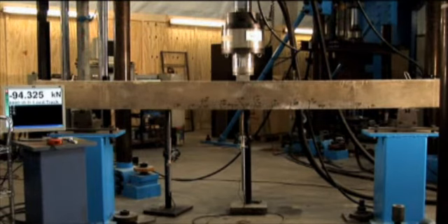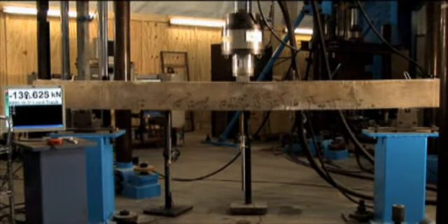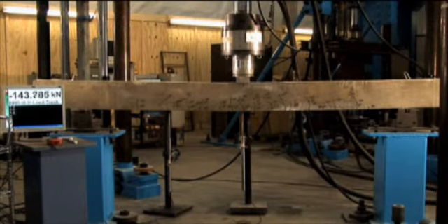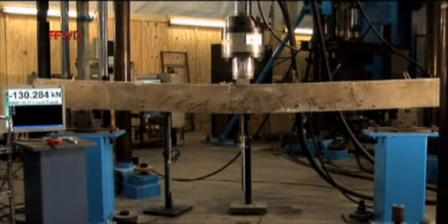As the beam approaches failure, crushing of the concrete occurs, leading to some limited ductility as shown by the plateauing of the load deflection plot. However, the steel reinforcement remains elastic and does not contribute to the ductile behaviour. Spalling of the concrete leads to failure of the beam.